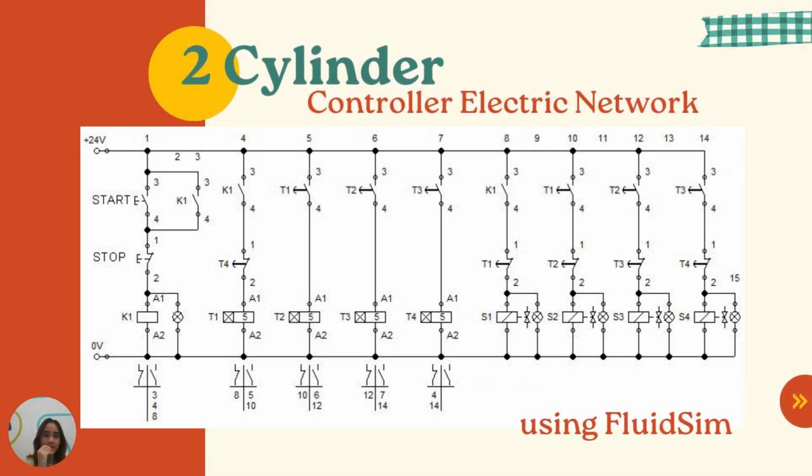Here is the two-cylinder controller electric network using FluidSIM. When designing the ladder PLC program, it is better to simulate it first in the FluidSIM application program. Using TDR, making an electropneumatic circuit in the FluidSIM application will facilitate the creation of the ladder PLC program in the CX-Programmer application program later. So the electropneumatic controller circuit using the FluidSIM application program uses the TDR component as shown in the picture of the circuit.